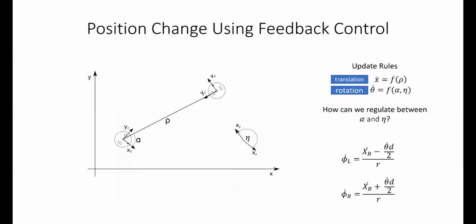In particular, we feel that everybody's fairly confident with computing their sources of error. And the majority of the questions that we've gotten are about these update rules. So what does your feedback controller actually look like? And what does all of this mean? What we're doing is taking our sources of error, and then we have to map all that down into these two translation and rotation components.